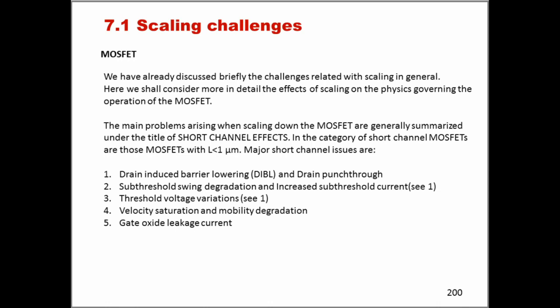So here we would like to have a more detailed look at the specific issues that are related to MOSFET devices. The fundamental problem goes under the name of short channel effects. And the MOSFET transistors that suffer from short channel effects are all those transistors that have a channel length that is below 1 or 2 microns.